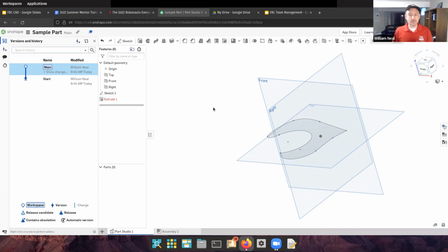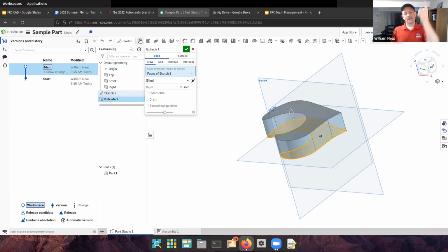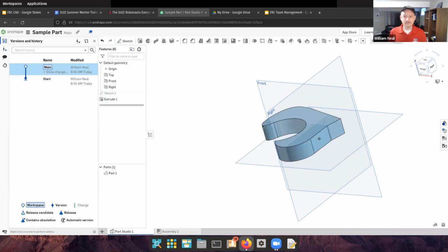And you can see that's what happened before when I was playing around with the other things. I did not have my sketch selected. So I'm just going to delete this with a right click and delete. So let's select this sketch and now we extrude. You see right away it extrudes. So we'll put in a 20 for the 20 millimeters and you see a 20 millimeter extrusion has happened. There we are. I have my shape.